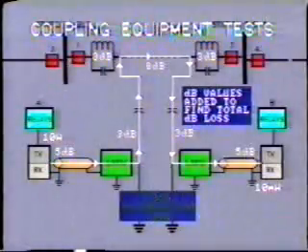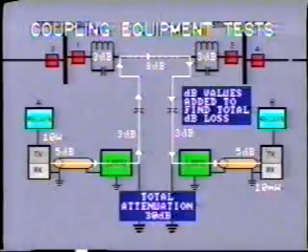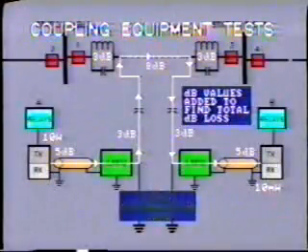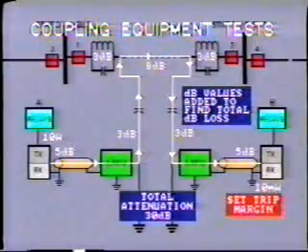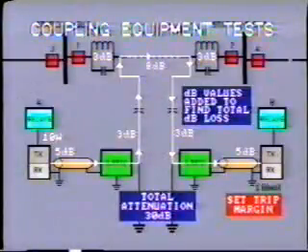Measurement of signal loss end to end with the carrier in service and at different frequencies. Adjustment of trip margin at the receiver.